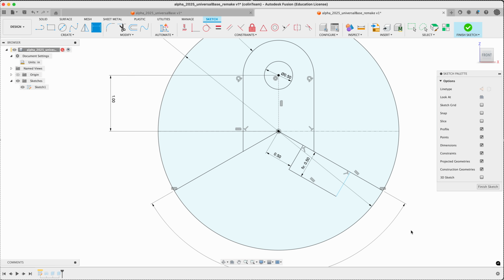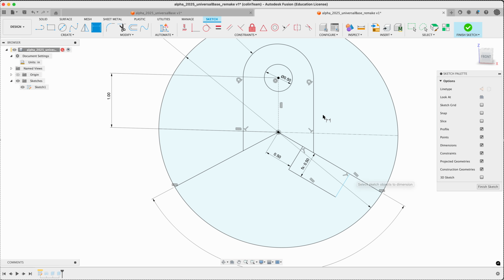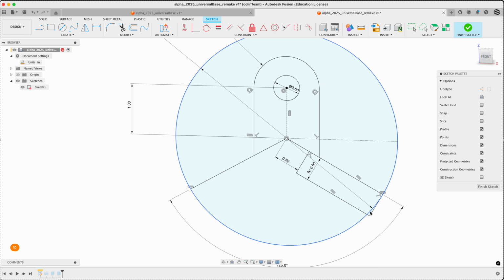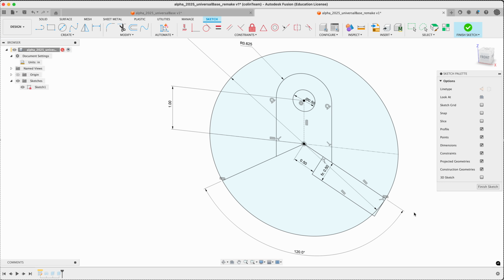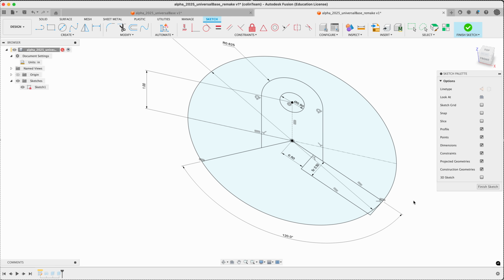Now, how do I completely define this without getting carried away? Well, I can just put this on this vertex on the circle. Let's make sure that no matter how big the radius of the circle, this big circle, this will always protrude slightly. So this will make sure our cut works. We're going to do one and come back and do the other, so make it a point.